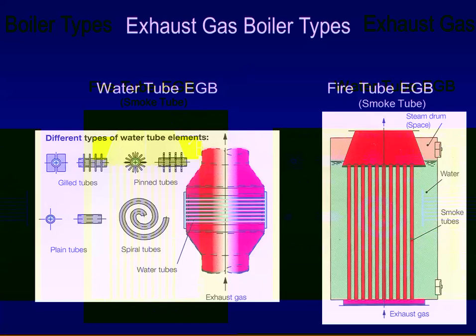Typically, your reaction should be, of course, to notify the chief engineer and the captain that you believe an exhaust gas boiler fire is present. When safe, they will shut down the main engine. I would typically suggest that you have tarps or canvas made to put over the top of your air cleaners into your turbos so that you can stop airflow through the exhaust gas boiler. That's a primary: you want to starve this fire of oxygen. If you have a CO2 system, then you can deploy the CO2. I haven't really seen that as often.